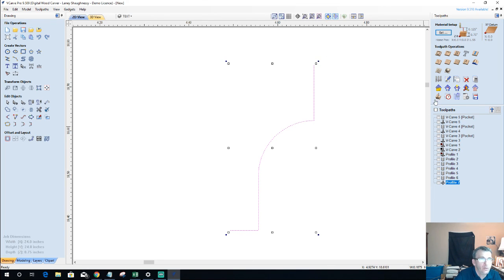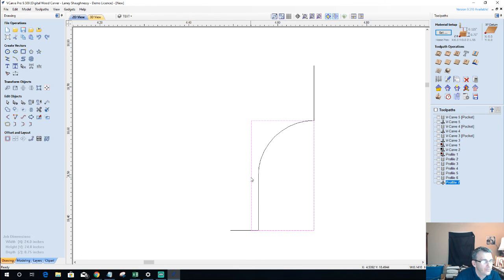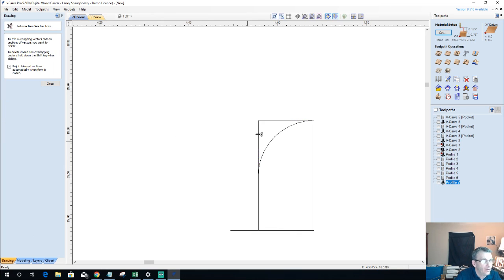When you do outside of the line, that means it's going to cut on the outside of the bit. Well, we want to step over this 1/8 of an inch from the outside of the bit to the inside of the cutter, so that it's coming in and rounding off that corner of our board. Let's try that again. How about that? So it's cutting off that roundover of our board. And if I were to simulate this with a little trim, we get that nice roundover, right?